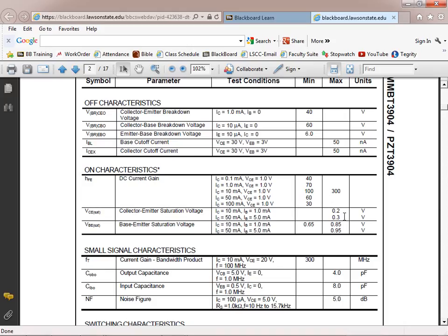Or something between the collector and emitter is shorted. If you got a switch, you're going to measure 0 volts across that thing when it's closed, right? You understand that. But a transistor, you'll never measure 0 volts between the collector and emitter when it's turned on. You'll measure less than 1 volt when it's saturated, and then you'll measure your collector voltage across the transistor when you're cut off, and then if you're in the active region, it's going to be somewhere between those two.